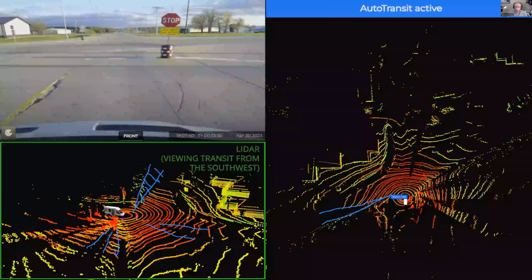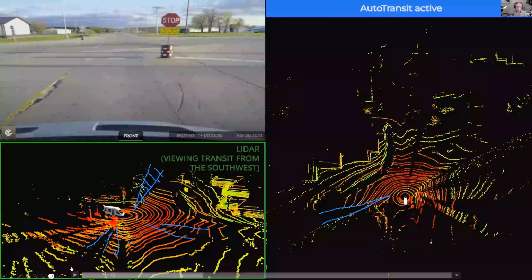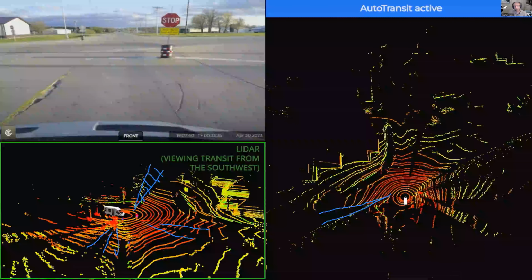Now that's problematic because all of the westbound traffic that's coming off of this road is essentially driving down this blind spot. The way that perception works in Apollo is that it's taking a look at the history of objects as they move in the world around you. So by effectively being in a blind spot, the system doesn't know that a car's oncoming.